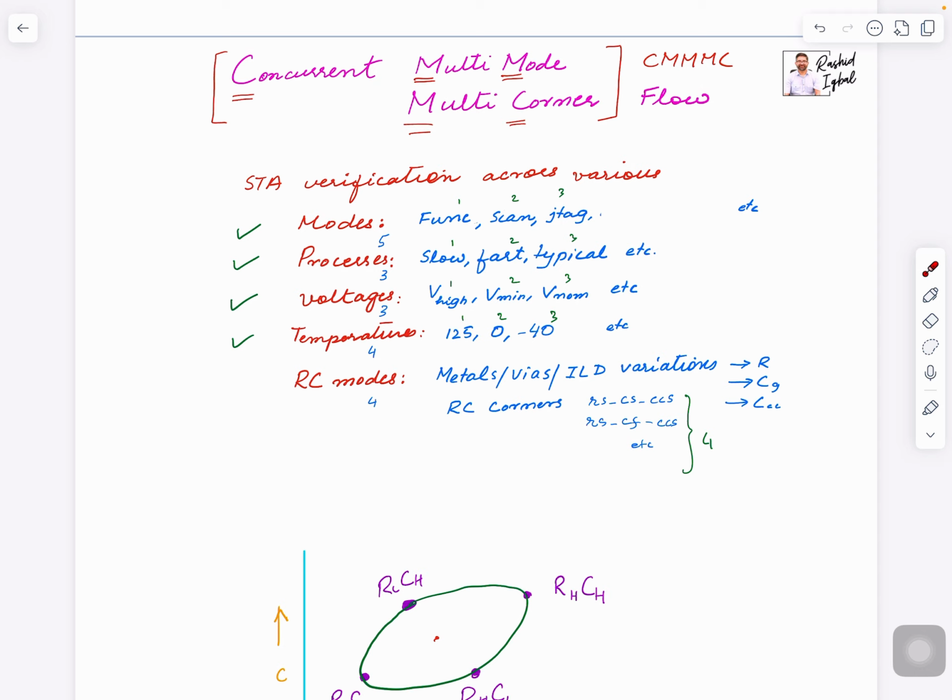The variation here is a device process variation. Device manufacturing can bring very different variations in channel dimension and in threshold levels, which means different doping levels, and different caps and all that. We did discuss all the process also in the block timing flow. So this is not on die, this is inter die. I pick slow, fast, and typical. You can add more.